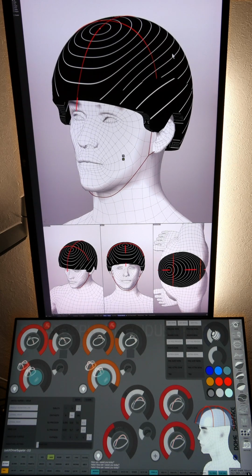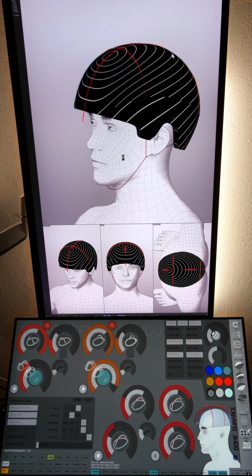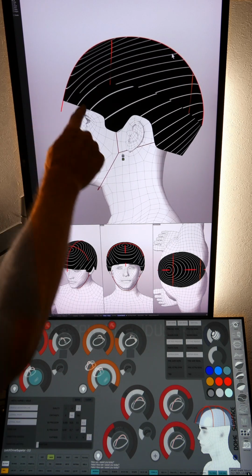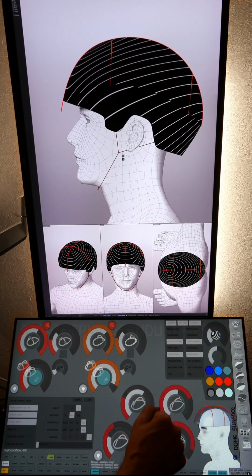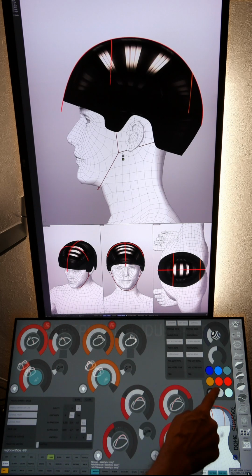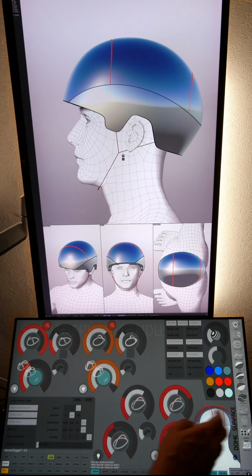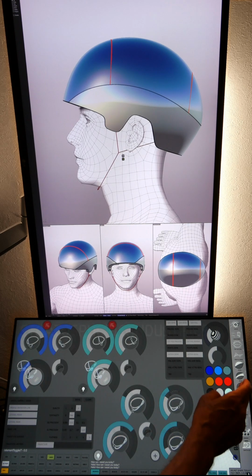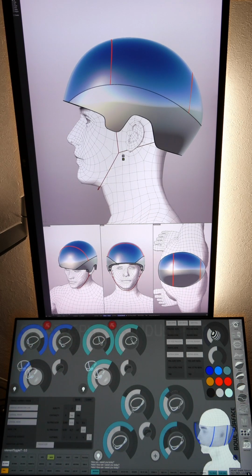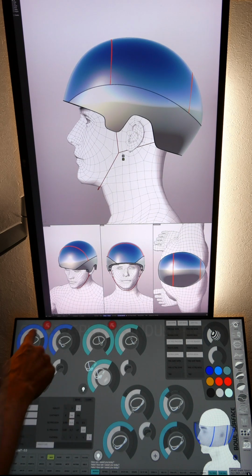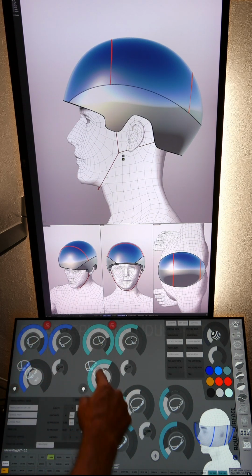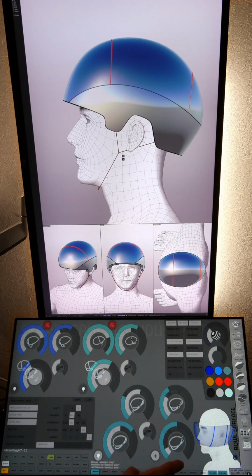There are different controls now. There are controls on the cut line of the helmet. This obviously is the cut line of the helmet. Turn off the display there. We'll go back to a nice glossy display here. Turn off the crown line. Also, we have the crown and we have the bowl. The bowl is designed to be almost the same as the crown. The controls are there. This controls the front lateral curve, rear lateral curve, and the overall bowl profile.